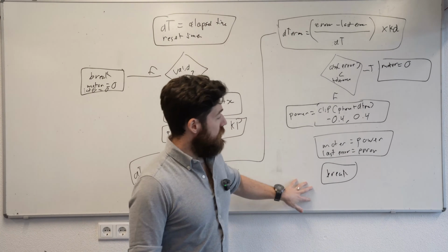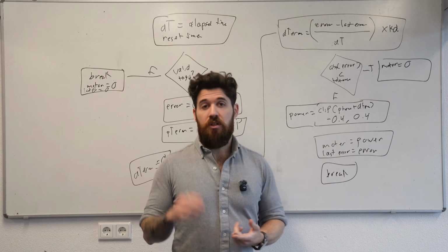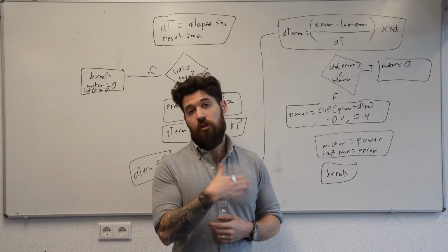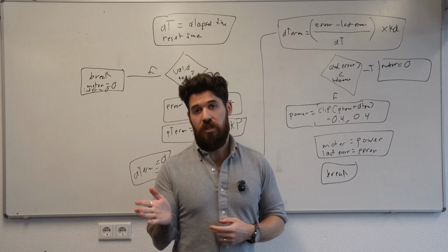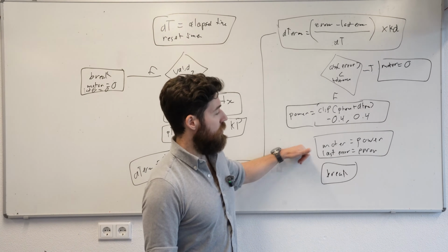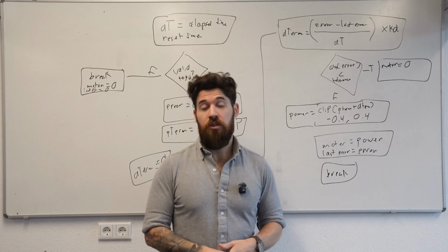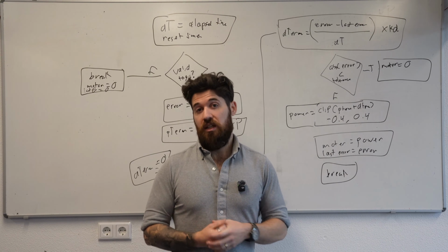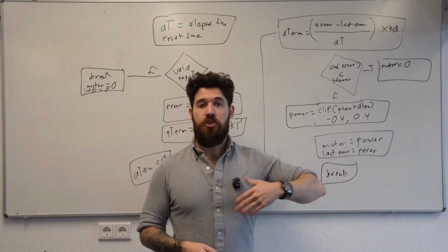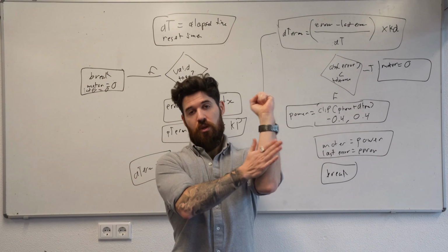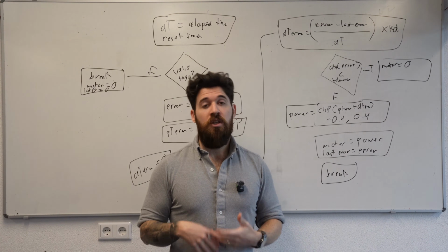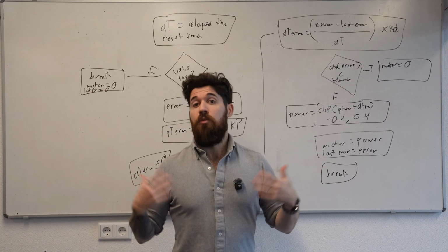So some ideas for how you might handle that: you could use an encoder on the motor, and once the encoder gets to a certain tick, you're no longer able to rotate past, and then you'd have to rotate yourself manually back in order for the P controller to get plugged back in. So that could be a quick safety before you actually set the motor power as well. You could also have a magnetic limit switch or a standard limit switch on it so it can't rotate around. You can have a physical stop with a sort of hard beam, so when you hit that beam, you just physically can't rotate anymore either. So that's another option for ways that you could make the system a little bit safer.